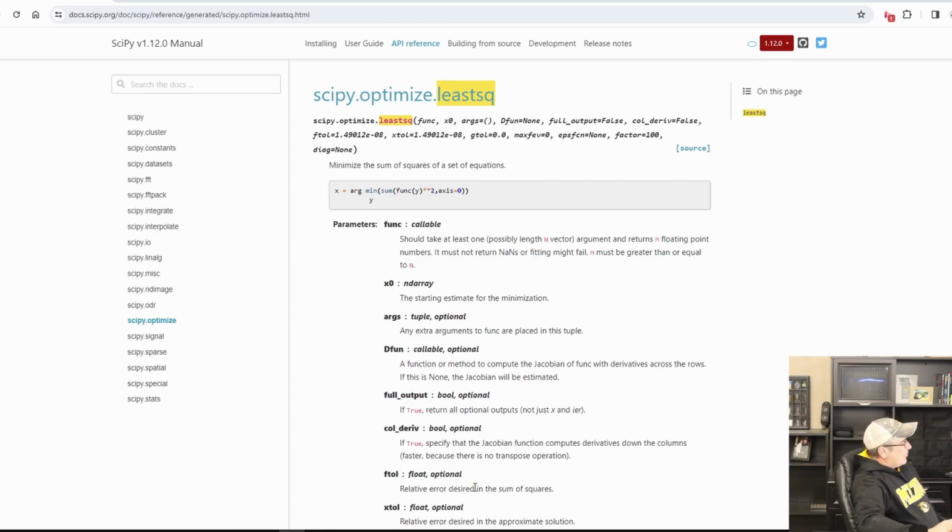And then we also have to give the function a tolerance limit. So this is going to go through that iterative process, and it's going to try to converge on a solution. And so we have to give it a tolerance band to say when good enough is good enough. So once our error in our solution gets down to a small enough value, we're just going to accept those results as accurate values. And so those are the only inputs we're going to use, and everything else in this function we're just going to leave at the default values.